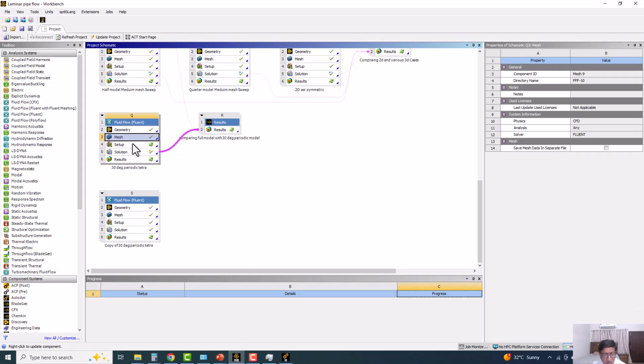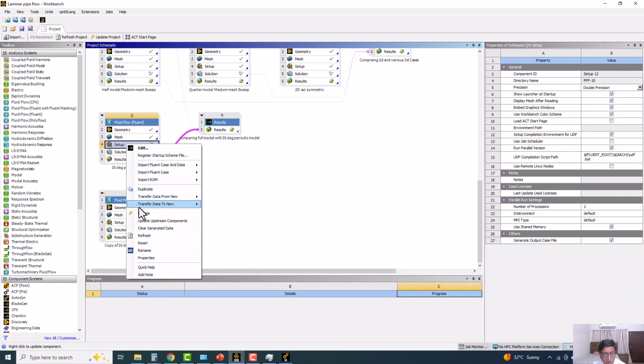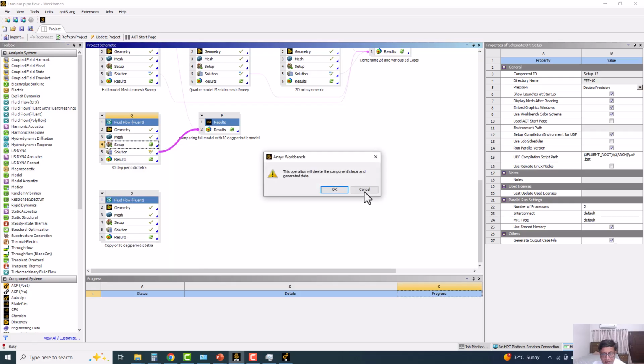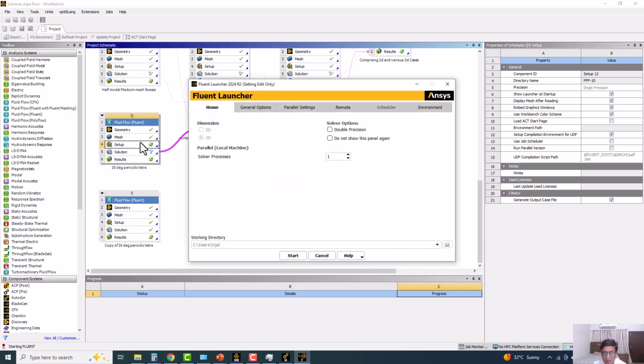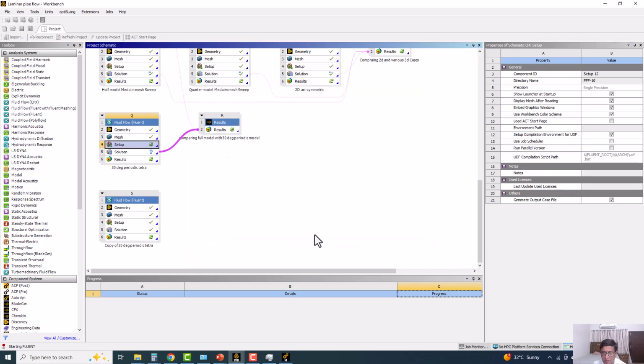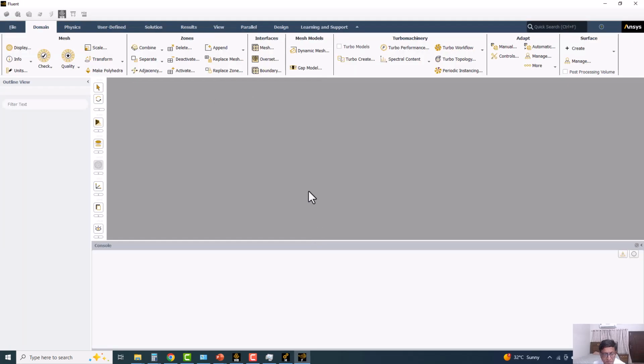In this step, I will show you completely. I will reset the Fluent part and start from scratch so that I can show you the different commands here, because putting the boundary conditions and the material properties is very simple. There are only 2 or 3 things to be put there: laminar flow, material properties, the boundary condition like a velocity inlet. The main and important thing is the periodicity in the mesh that has to be done.